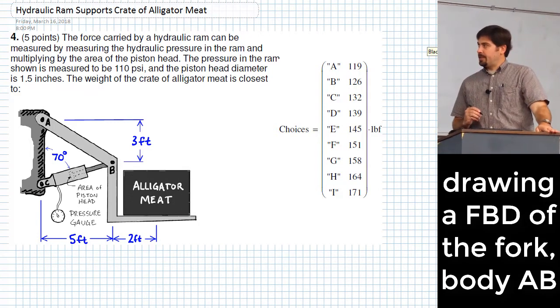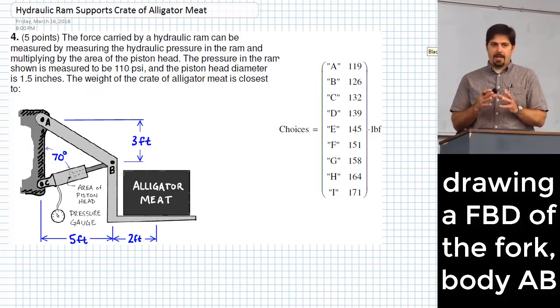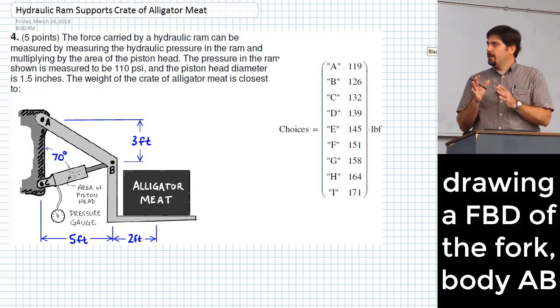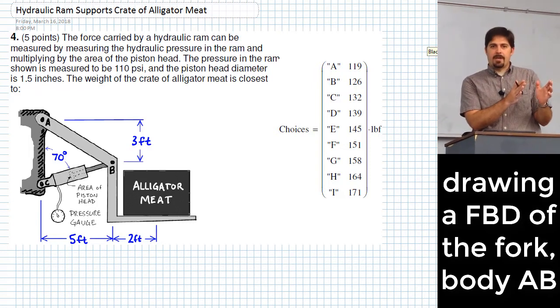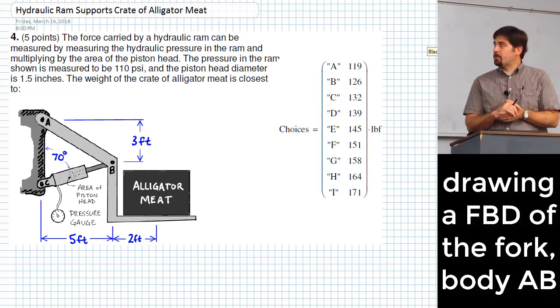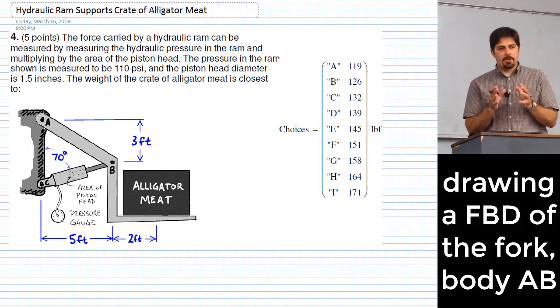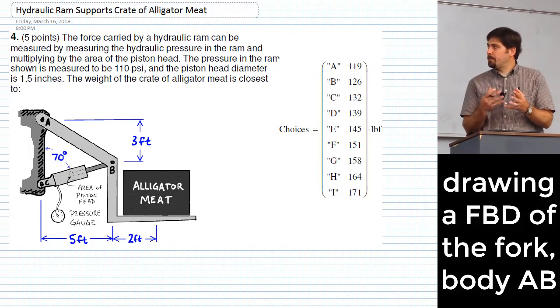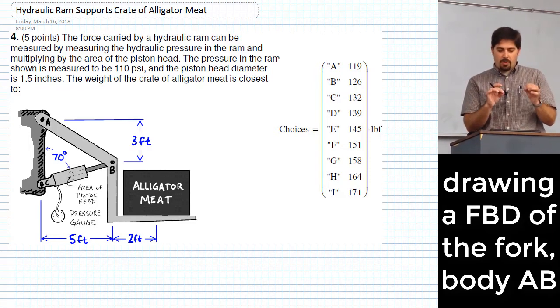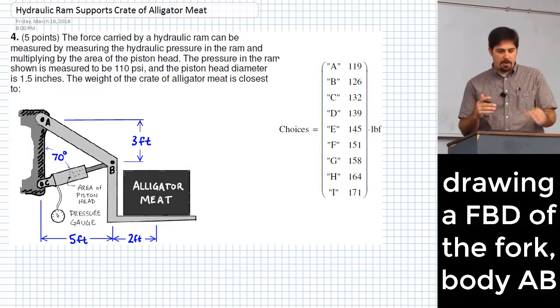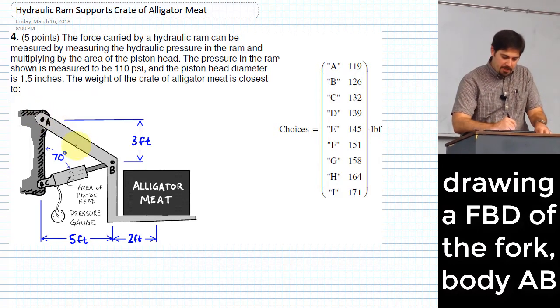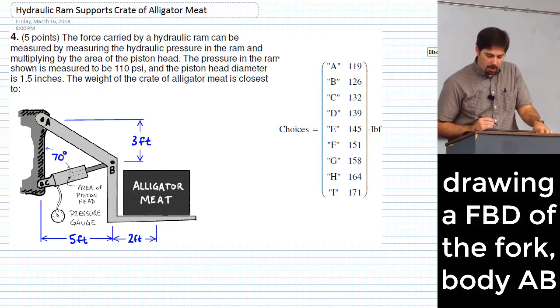One thing that I'll show you here is if you have time, I actually always prefer to draw the free body diagram so that it looks accurate, so that the body itself looks like the actual body. But if you are trying to do a problem quickly, the most important thing for your free body diagram is to make sure all of the points that you care about are correctly represented relative to other ones, and just draw as simple as possible something that connects all of those dots and show that as your body. So what I'm pointing out is that you don't necessarily need to draw an accurate fork exactly like it's shown over here. What do you think is important to draw?